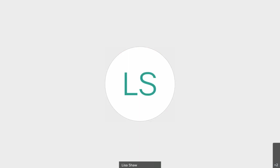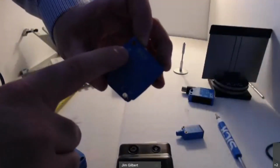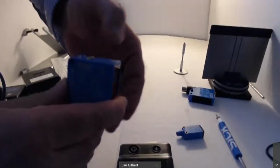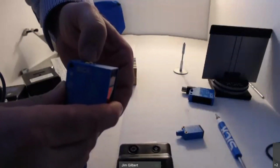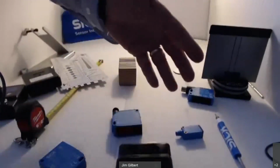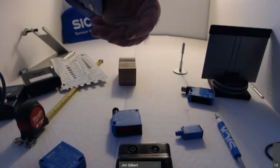Great. Another question from an attendee is, can the push buttons on the sensors be locked out so the operator cannot adjust them? That's a good question. We get that a fair amount. Some of our sensors do have IO-Link built inside, and you can see the IO-Link symbol. In that case, you can use IO-Link or set up through the PLC to essentially deactivate the manual button. In a lot of cases, an OEM will build a machine and they want to keep it set up that way so it's locked out. That would be one way that you could do it.